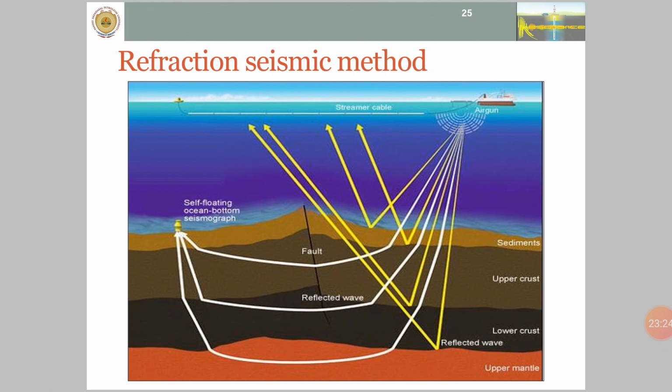Here is an understanding of the refraction seismic method. These are employed, as I told you, mostly to understand the low velocity layer. There can be a couple of layers within the low velocity layer. We have to understand how many clay bands remain in the low velocity layer, and that helps us understand the subsurface picture better. That helps us drill shot holes which should be below the low velocity layer for